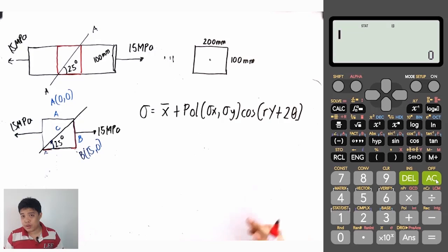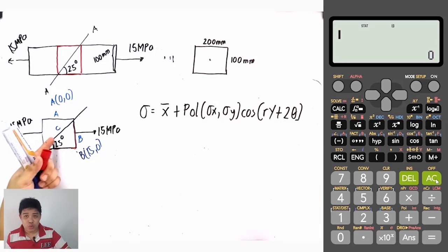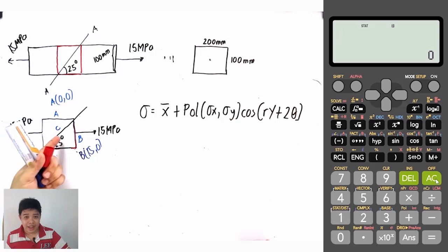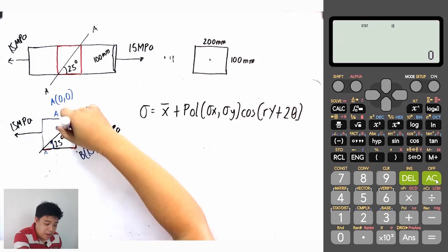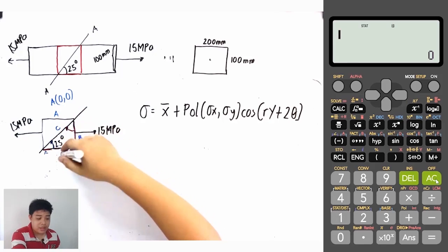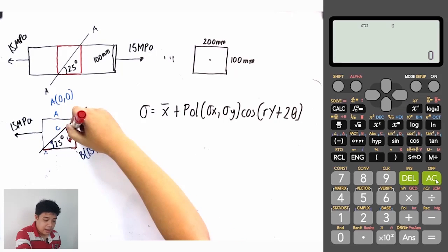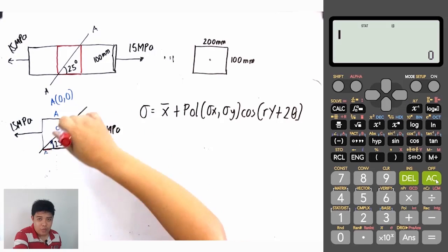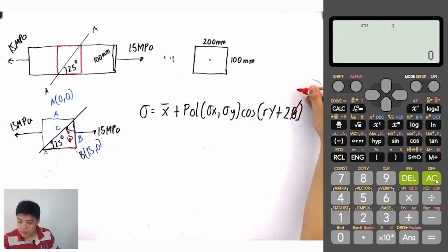We need the reference plane for the proper sign of theta. So, if you want to know the angle towards C, you start from our reference plane B. If this is 25, of course, the complement of 25 is 65 degrees. And from B, you have to rotate clockwise. So, for clockwise, that's negative. So, this theta will be negative 65.